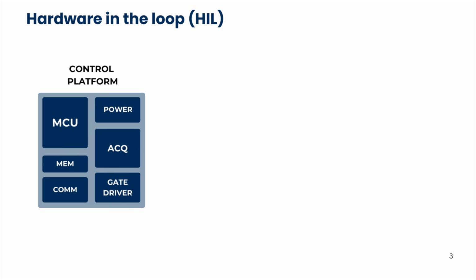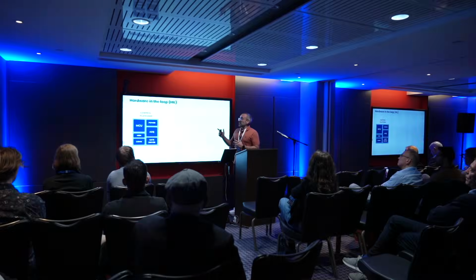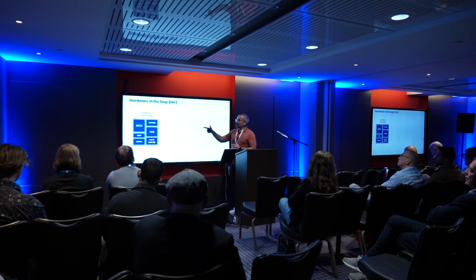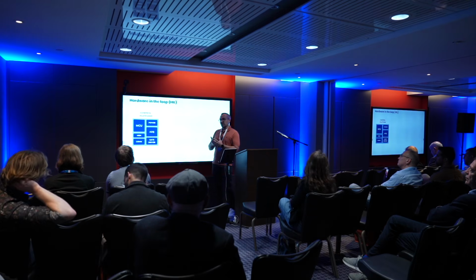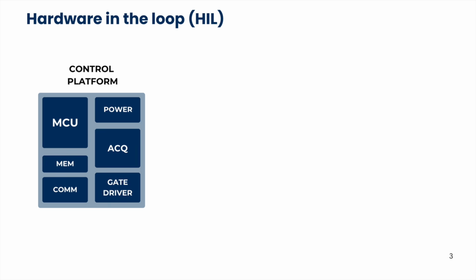So imagine that you want to implement a control algorithm to control a power supply. A power supply will be, for example, a power stage of several kilowatts or even several megawatts. In order to perform that simulation, you would need, in the first place, the control platform. The control platform will be based on a MCU. Also, you will have some memory in order to store your algorithm and some kind of communication in order to communicate with the external world.